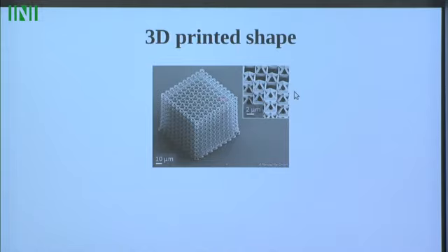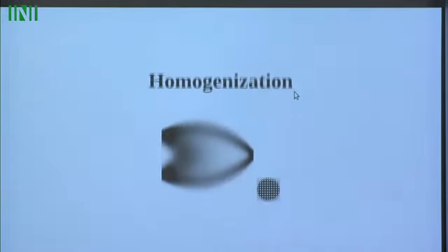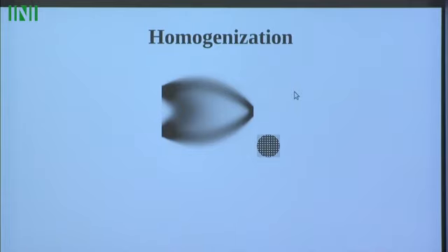and the natural tool to treat the direct problem or the optimization problem is obviously the homogenization method. Geoffroy is a kind of specialist of this kind of method. The idea in this case is to describe locally the shape by a density. Here I have represented the density of the optimal composite shape.